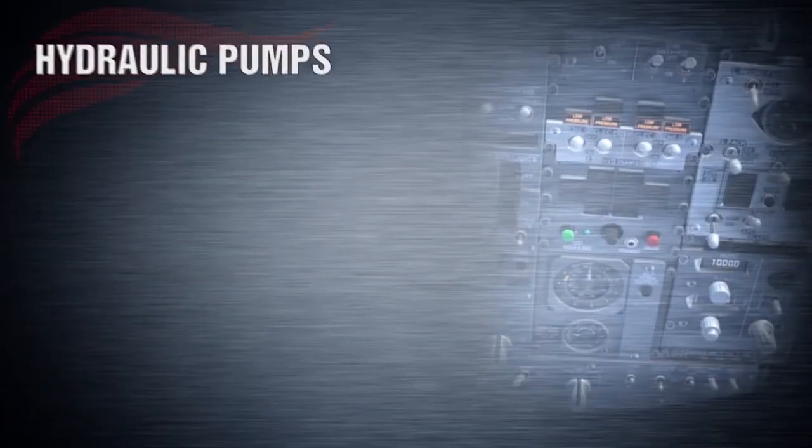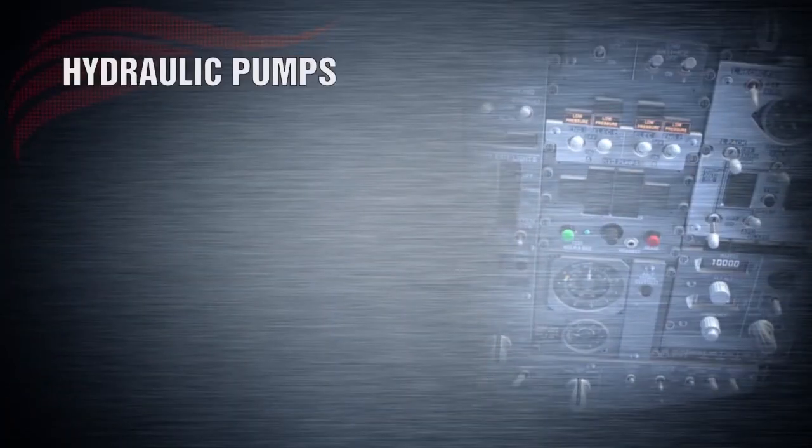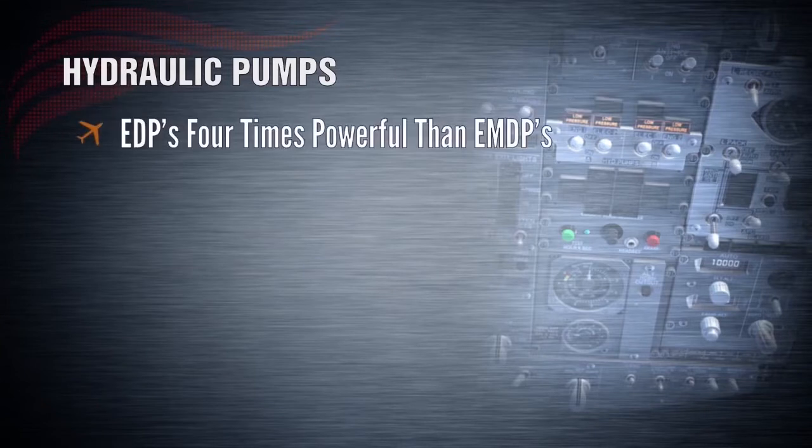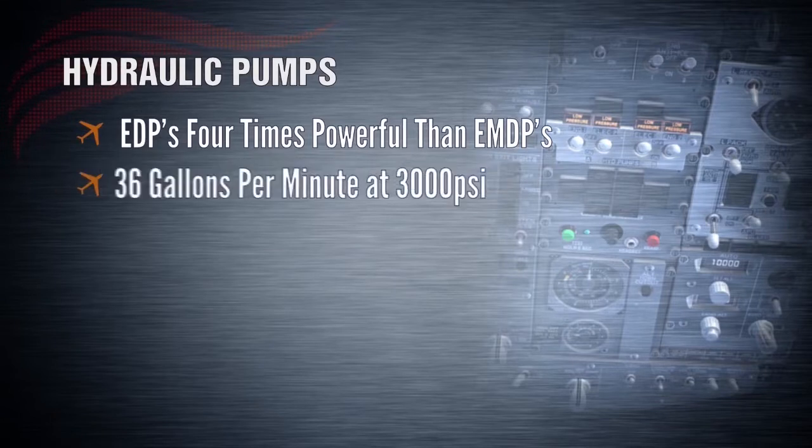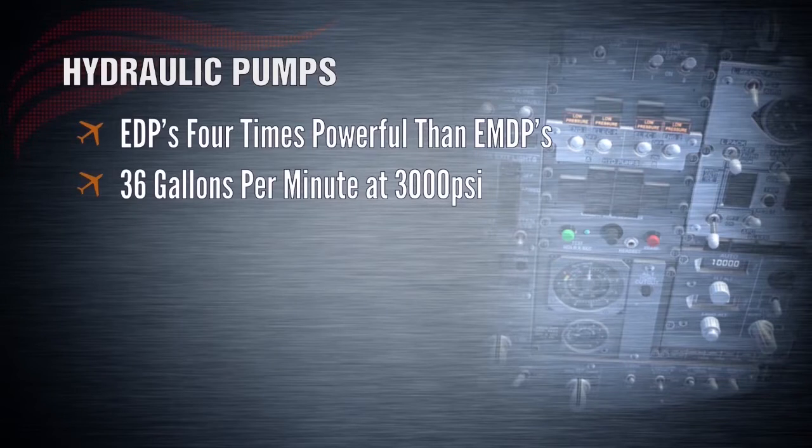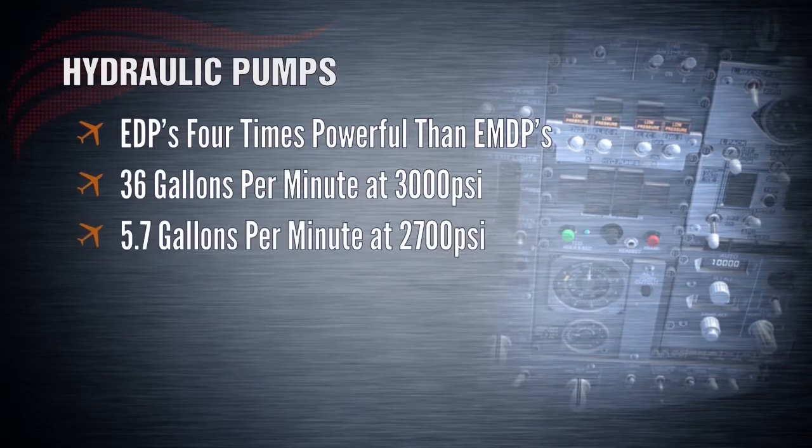All four pumps supply approximately the same pressure to the hydraulic system, but the engine-driven pumps are much more powerful and put out approximately 4 times more volume than the electric pumps. The engine-driven pumps are rated at 36 gallons per minute at 3000 psi, and the electric pumps are rated at 5.7 gallons per minute at 2700 psi.